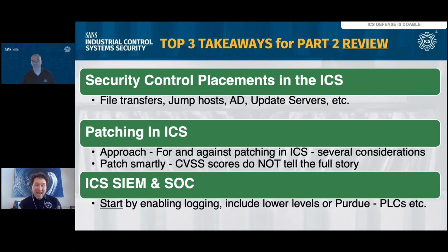We moved on, and we talked about patching as well, and the crux of that conversation is really about patching smartly. We want to make sure safety is still number 1, so CVSS scores are not the full story, especially in ICS where you have to consider safety. And of course, we are seeing adversaries really focus on abusing industrial control systems. So there could be a vulnerability that even if you patch it, there is still a risk there with an adversary abusing an HMI, as an example. So CVSS scores are not the full story.